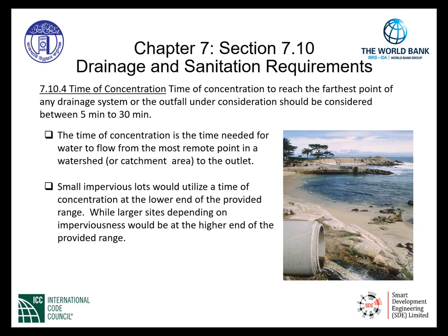The time of concentration is the time needed for water to flow from the most remote point in a watershed or a catchment area to the outlet. Small impervious lots would utilize a time of concentration at the lower end of the provided range, while larger sites, depending on imperviousness, would be at the higher end of the provided range.